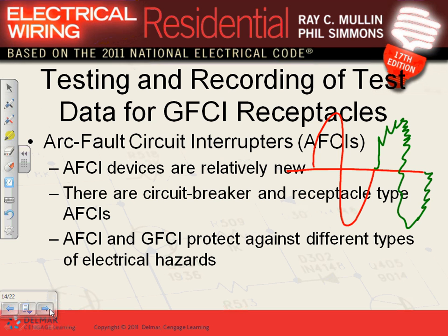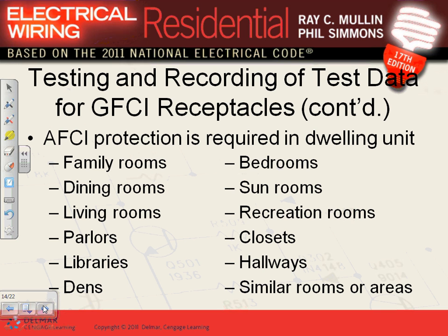So the smarter device, the arc fault circuit interrupter circuit breaker, looks at that signal, analyzes it electronically, and comes up with a decision that, guess what? This branch circuit must have an arc fault somewhere. So what do you do? You trip. That's basically what it's looking at. If it doesn't trip, what could happen? Arc, heat, fire, and so forth. Okay, we got that one.